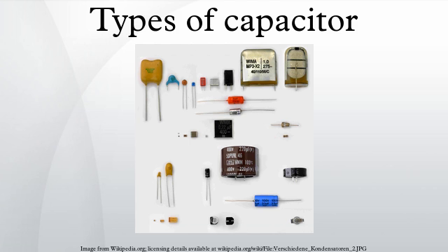Unlike batteries, in these reactions, the ions simply cling to the atomic structure of an electrode without making or breaking chemical bonds, and no or negligibly small chemical modifications are involved in charge-discharge. The ratio of the storage resulting from each principle can vary greatly, depending on electrode design and electrolyte composition. Pseudocapacitance can increase the capacitance value by as much as an order of magnitude over that of the double layer by itself. Common capacitors and their names.